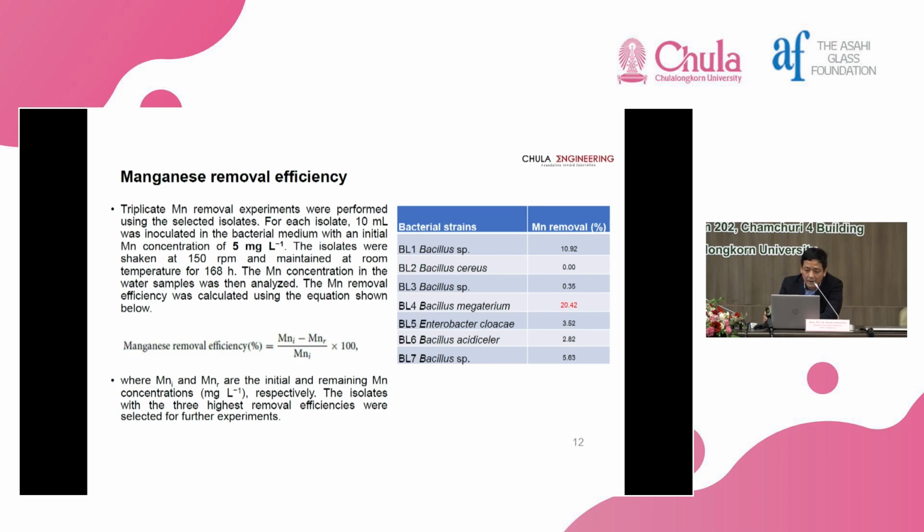And we found that there's a distribution of the removal capacities of manganese by Bacillus. The fraction is 4, as presented in the table, but it contributes only 20% of the total removal. Some of them are not just targeting manganese removal, but some of them can even remove iron. So the removal of iron and manganese occurs together with specific types of bacteria.